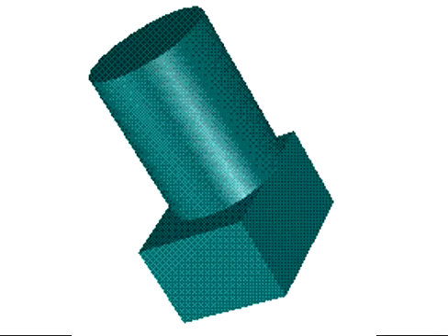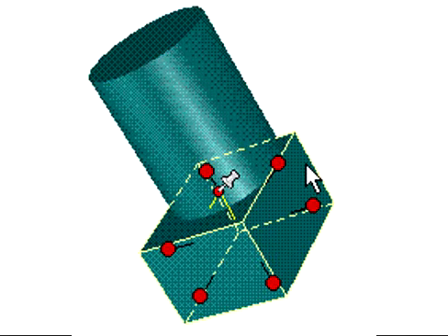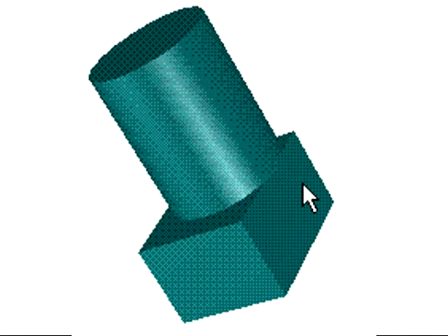You can work with any part of a model or the model as a whole. To work with the model as a whole, select it by clicking it once. To clear the current selection, click in the blank area of the scene. To work with a single IntelliShape within a model, click it twice. To work with one surface, edge, or vertex within a shape, click it 3 times.